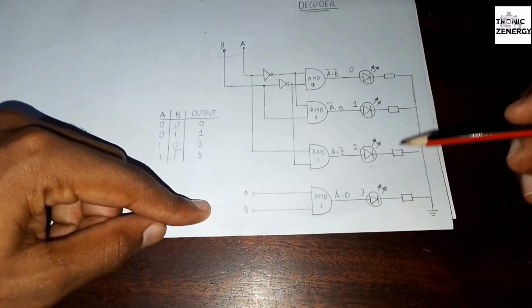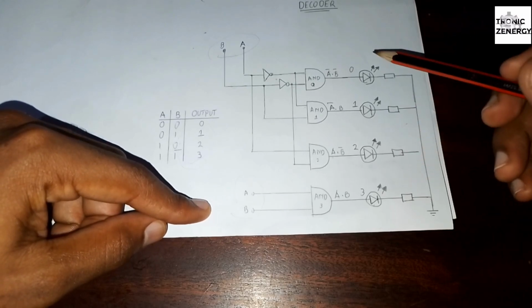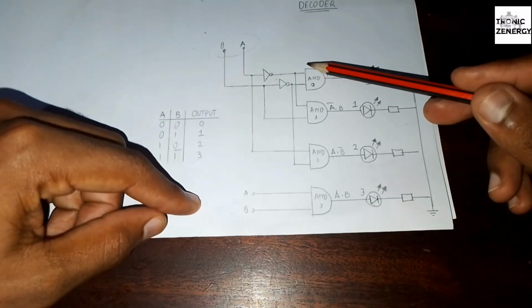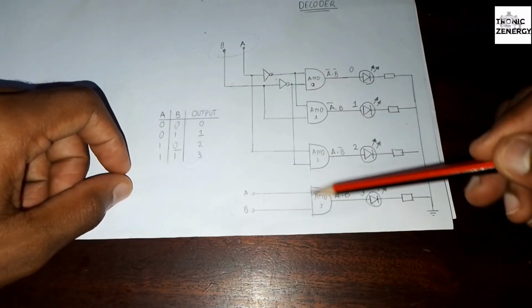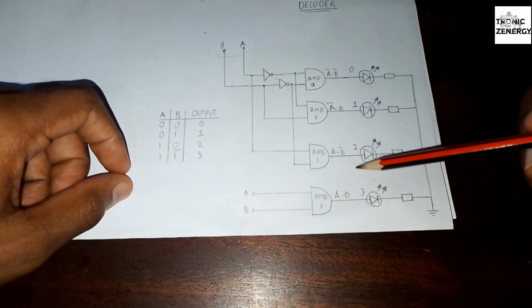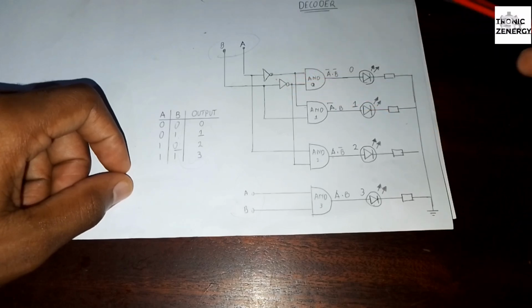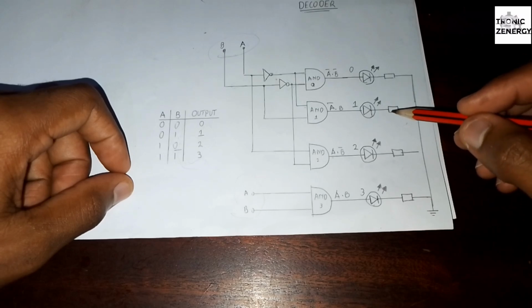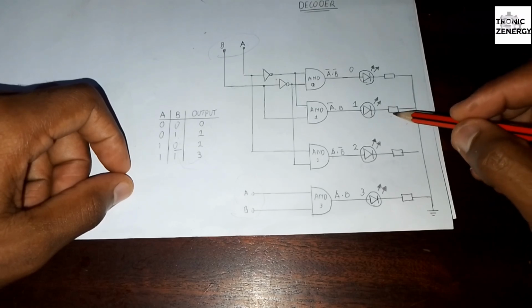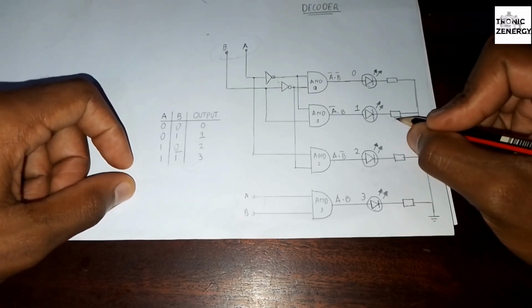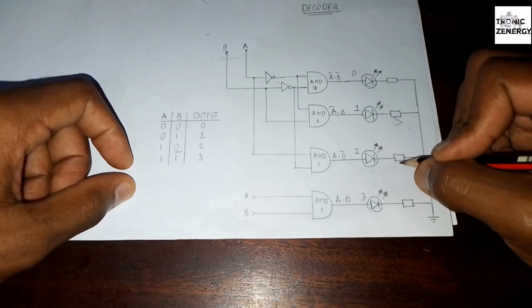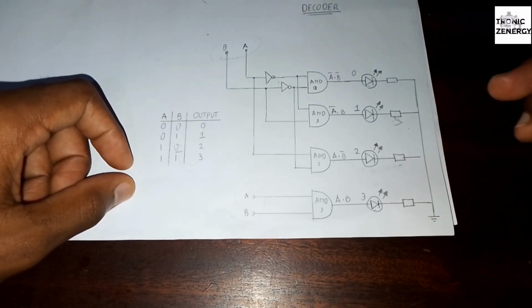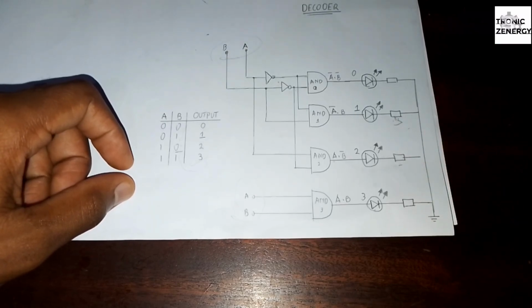And it's just a simple circuit using an IC. My IC has all of the four AND gates, and I'm also using an OR gate to make this circuit. The LEDs require some protection, so I'm using 1 kilo ohm resistors to protect them against the currents of the circuit.